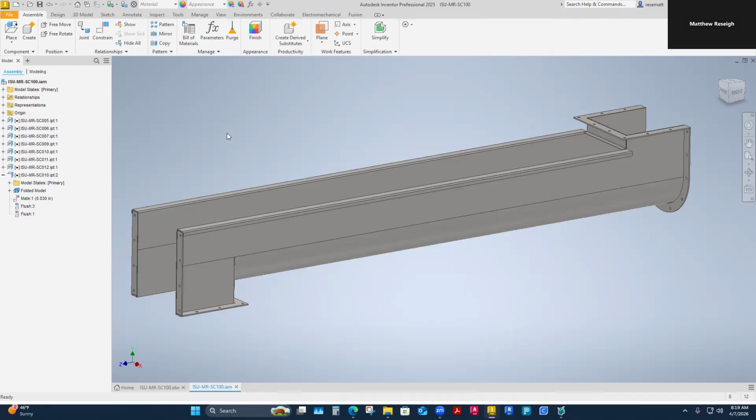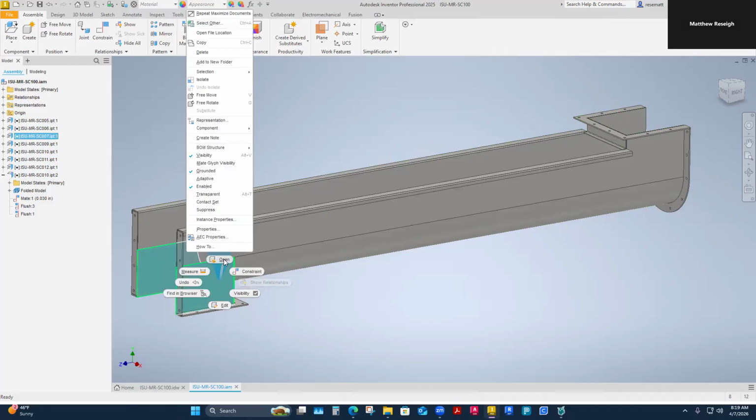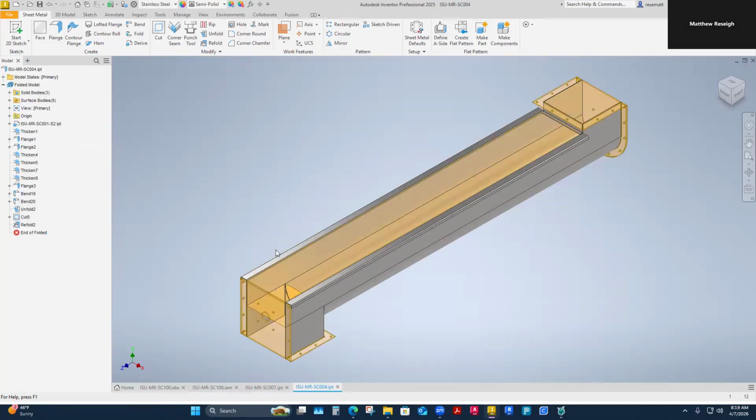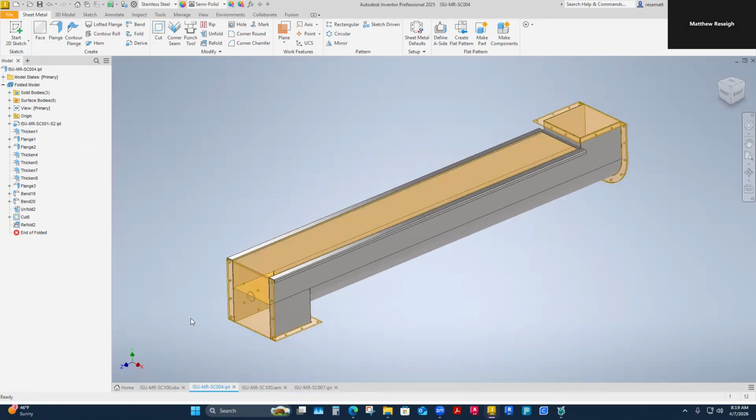Let's see. What's interesting is I can get to these individual parts. From here, you can't necessarily get to the base component, even though there was a base component and this was exported from it. If I want to get back to that base component, I can open an individual part that was created from it, and that base component shows up on the model list right here. This is how I would drive down and get to this part again to make my changes, which I feel is the upstream part from all of those. That's how I would normally navigate from the drawing to the parts.